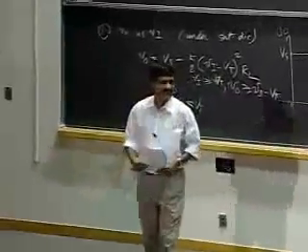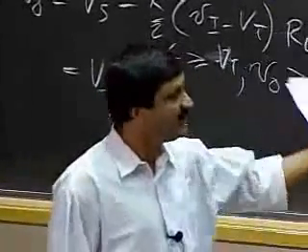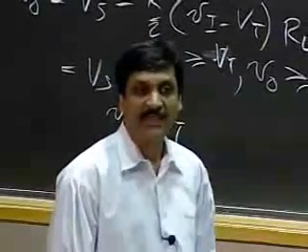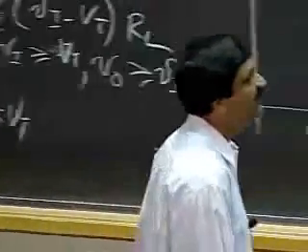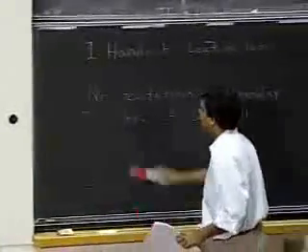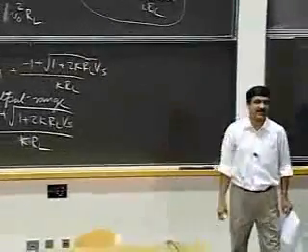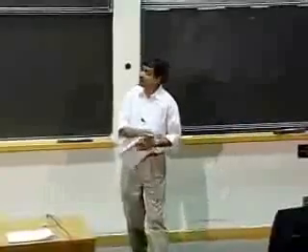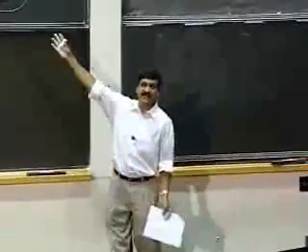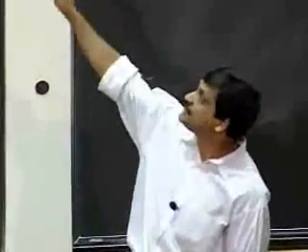Other practical devices like bipolar junction transistors, or other circuits and so on, can be subjected to a similar analysis, and you can find out the valid operating regions for that device or circuit as well. So as a next step, out here I began by looking at the transfer function, the V0 versus Vi curve, and used that to drive the intuition behind how we calculated the bounding regions.